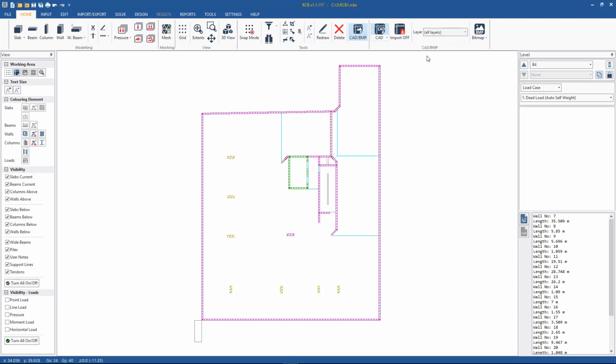And if we go back to all layers again, the next thing that we do, which isn't necessary for this example because the CAD files have been automatically lined up, would be to set a reference point. So sometimes architectural CAD files don't line up exactly, above and below, so we would have to set a reference point. But these particular floors, the basement floors, have been set up in CAD so that this rectangular box is always at the 0, 0. One of the upper floors we will have to shift, but for these basement ones we don't need to do anything, which we will see when we go on the lower floor.